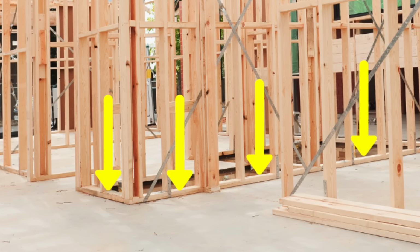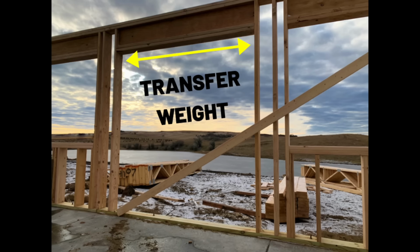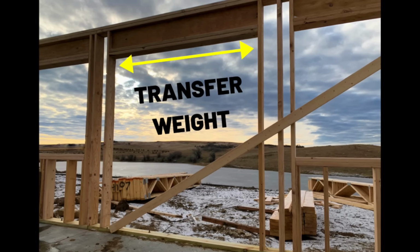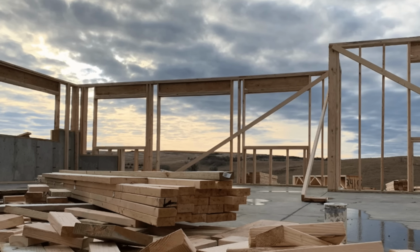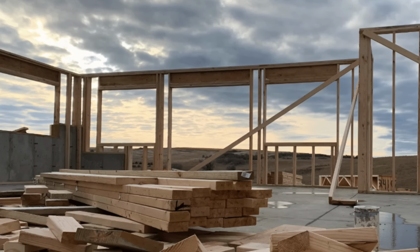These openings get special framing, and that framing has a complex system of names and functions. For instance, you've probably seen these pieces of solid wood facing outward above an opening. These pieces are called headers, and they're very important. Doors and windows create hollow space in a wall, which means that studs aren't there to support weight from above. So the headers transfer the weight that would be in that space out to the edges of the opening. Really, they act the same way that a beam or girder does to carry weight over a span. They're like a bridge that creates a safe hollow space for the door or window to sit inside.